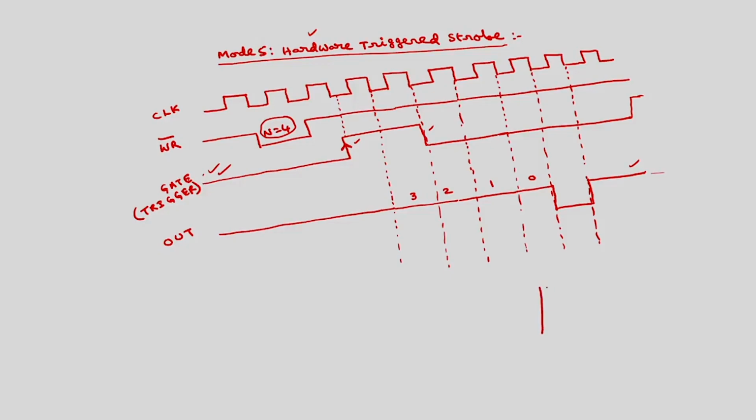Handshaking signal is something like, if I want to transfer the data between 2 devices, say microprocessor and peripheral, so initially the signals will be exchanged between these two before the data transfer takes place. Initially the microprocessor will request through this signal to get ready,